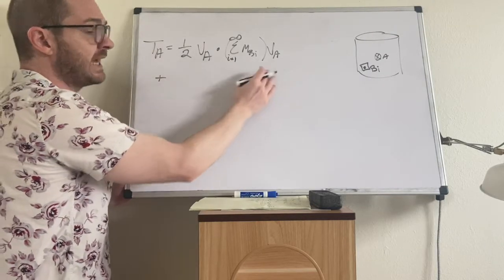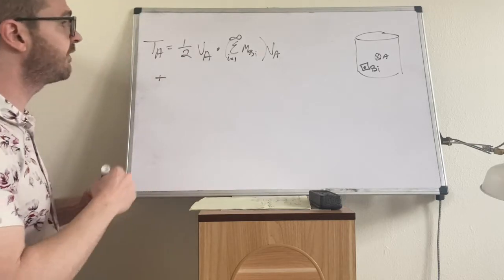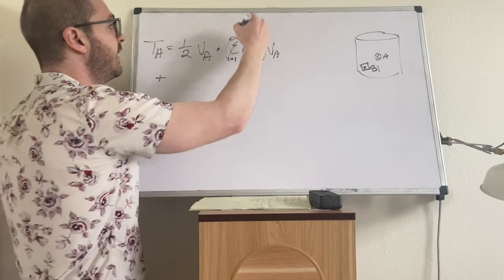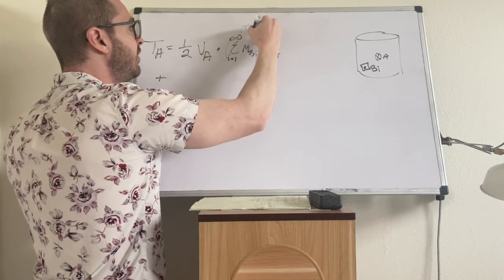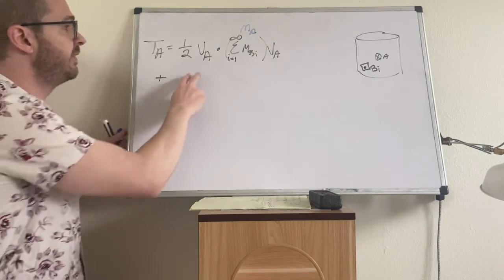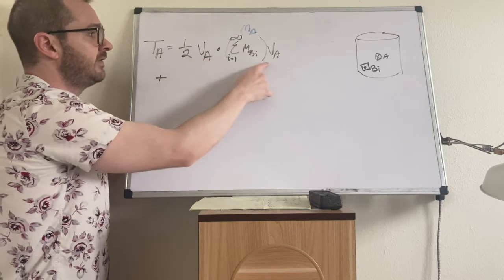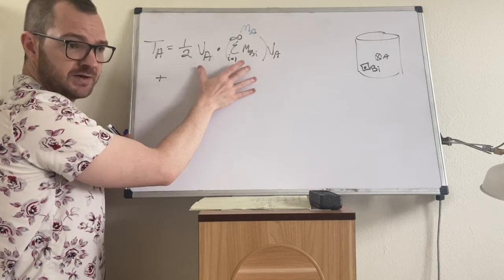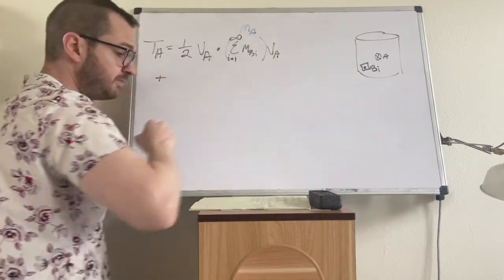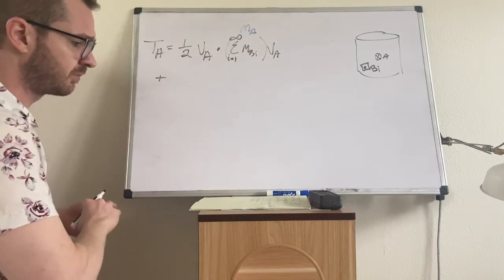This was the VA dot VA term. In this one, notice that everything is constant with respect to the summation with the exception of the m_bi. And if you sum all of those individual m_bi's, you get MA, the mass of the whole thing. So this expression is going to be 1/2 MA VA dot VA. This was the kinetic energy of the particle, but notice now we're looking at the velocity of the center of mass and the total mass of the whole thing. So there's the first expression.